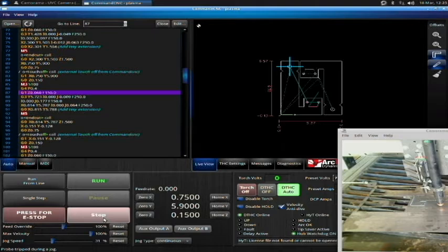It could be low air pressure. It could be you didn't have your ground connection connected. It could be you don't have the power on your unit on. In that case, lo and behold, the power is not on.